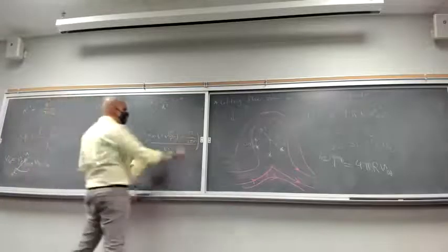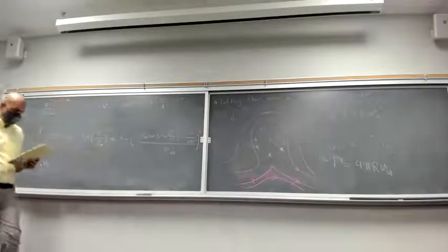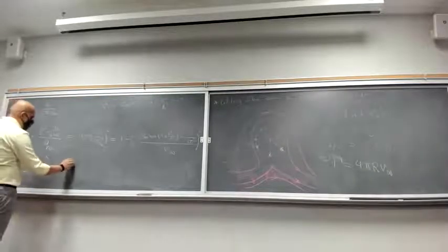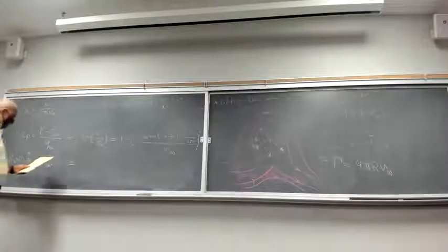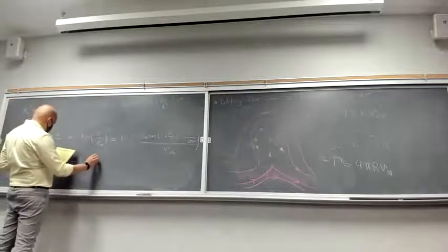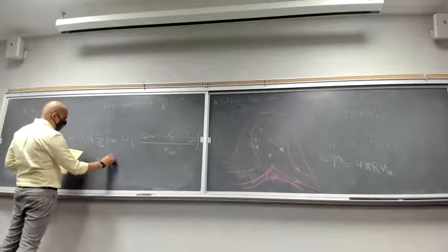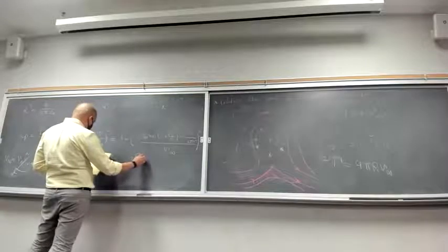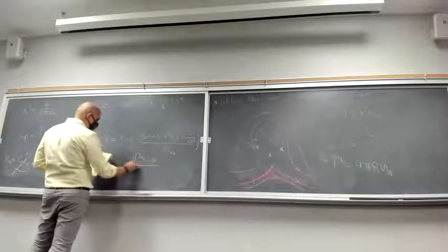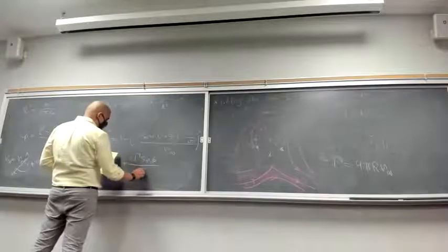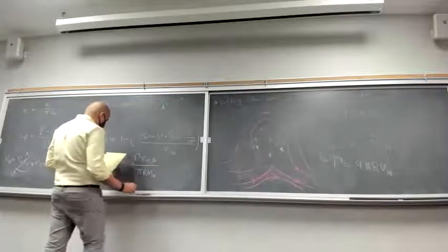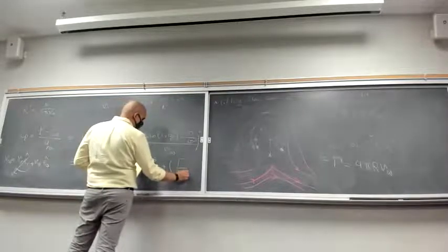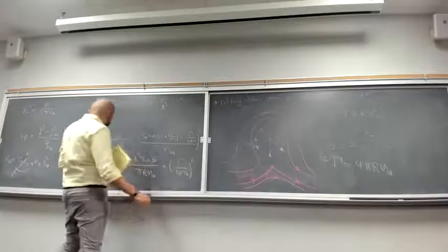All of that to the power 2. We can essentially raise this to the second power and eventually get this final value for Cp: 4 sine squared theta plus 2 gamma sine theta divided by pi R V infinity, plus gamma over 2 pi R V infinity squared.